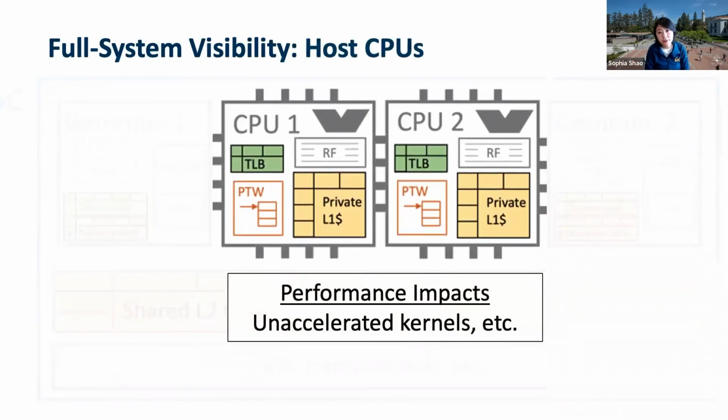Of course, there are also other considerations, right? A lot of the time we focus on accelerators, but of course, there is also the CPU component, where the CPUs are typically responsible for orchestrating different tasks onto different parts of the SoC and making sure all of them can operate correctly and in a performant manner, right? And sometimes we run into unaccelerated kernels, and we also need to offload them back to the CPU. So it is very important to think about the role of CPUs. And we also show the page table walker here, how we handle virtual memory. All of these are very important when we think about accelerator integration.